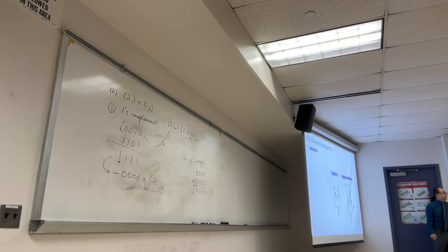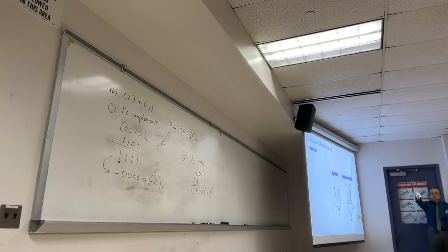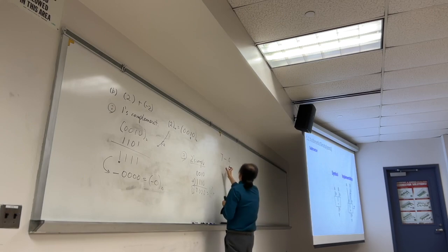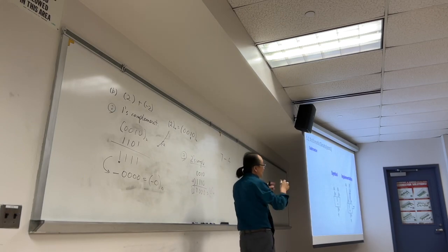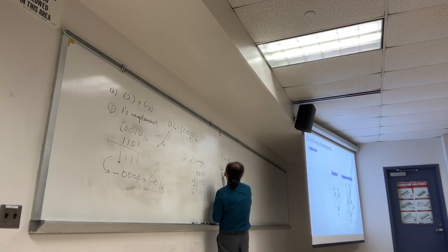And actually, in computer architecture, there is no subtraction. We have an instruction, but basically the subtraction is adding the first number and the 2's complement of the second number, right? Just what we did. We add 2 numbers. If it is a subtraction, for example, 7 minus 4, there's no subtracting hardware. They're always adding. How? 7 plus -4.